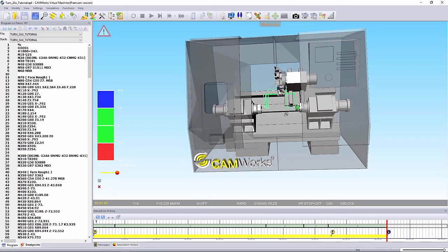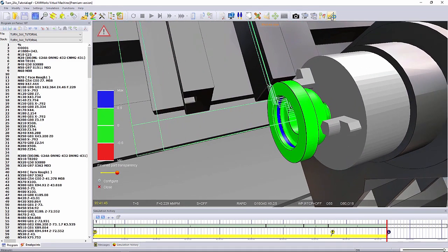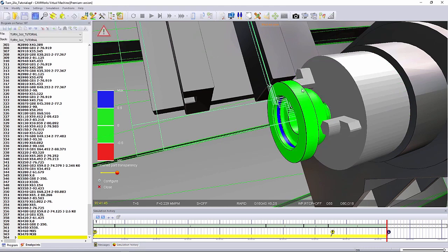When it comes time to taking measurements of my cut file, I can do that as well. If I wanted to pick up, for example, a radius, I can click 3 points, and it's going to create a radius for me to measure. And I can get an actual measurement of my file as it's been cut using the Gcode that's going to be loaded to the machine.